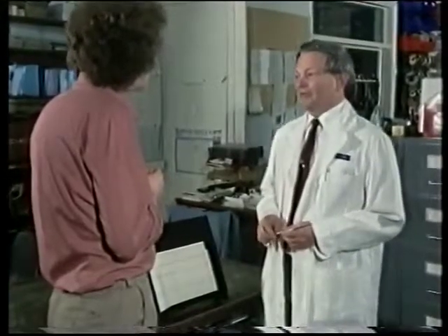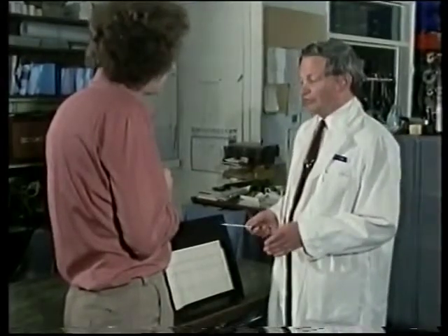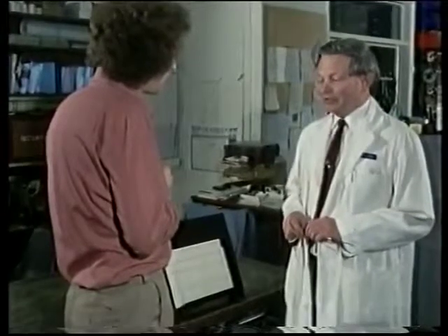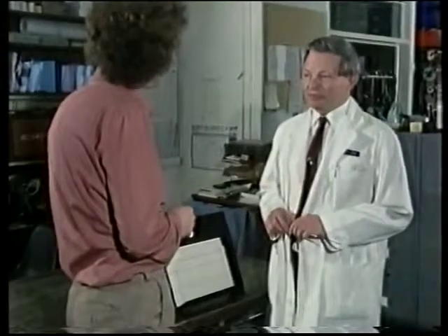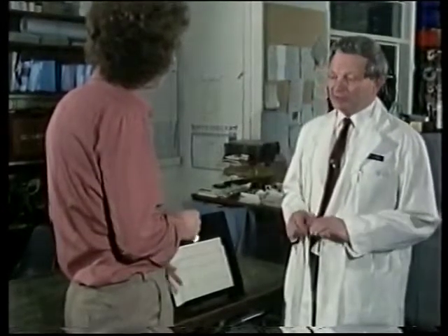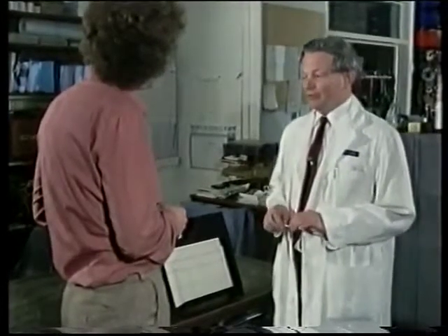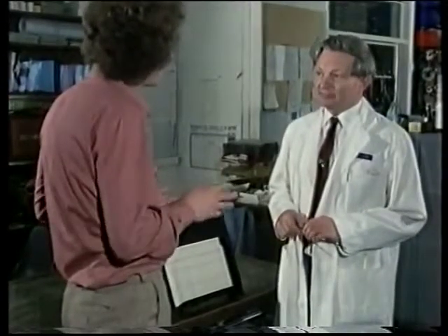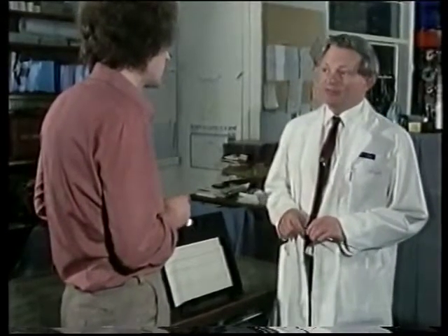Yes, we have several. In the first place, we have to be very careful about electrical safety, and we must isolate the patient very thoroughly, both from the mass of the equipment and from the mains electricity. Secondly, we only have about 1 to 3 millivolts derived from the patient, and at a source impedance of our electrodes, which are stuck on the patient, of about 40 to 50,000 ohms. And then there's always the problem in a large hospital like this with a lot of electrical equipment of interference from outside. So what sort of amplifier do you use then? So therefore we use differential amplifiers with screened input leads.